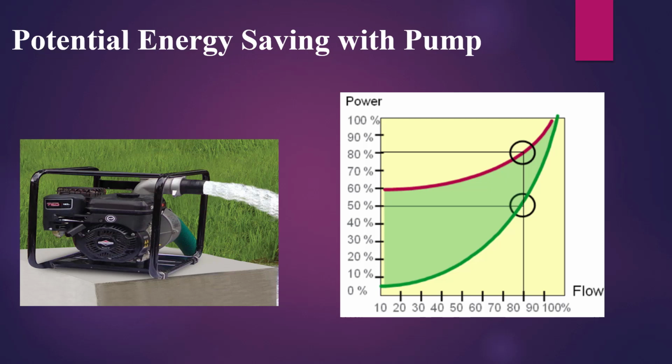How can we save up to 50% of the energy in water distribution? Let's replace the direct-on-line starting with a variable speed drive. The valve is no longer needed since the flow can now be adjusted by variable speed control of the pump. To vary the flow, the speed reference is adjusted. The difference between the green curve and the red curve represents the energy savings.